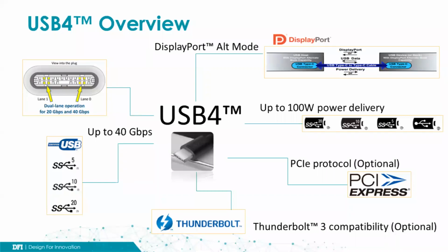In USB4, alternate mode is required, and the USB4 specification enables products to support DisplayPort alternate mode and Thunderbolt alternate mode. With 40 gigabits per second bandwidth, it can support 4K 60 Hz instead of previous USB 3.2 with 4K 30 Hz support. Depending on Thunderbolt architecture, USB4 also can support daisy chaining with up to 6 compatible devices connecting to one USB Type-C port.